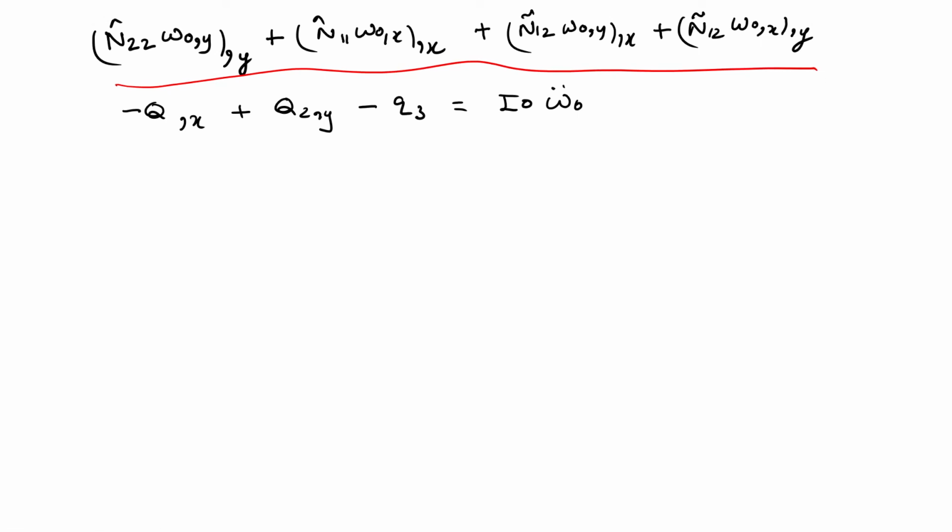So if you try to verify, these are the same partial differential equations for the case of a rectangular plate under FSDT, first order shear deformation theory. So you will get a similar set of equations, like the first equation is nxx comma x plus nyx comma y. Let us say only for the static case, just simply the static case and only transverse loading.